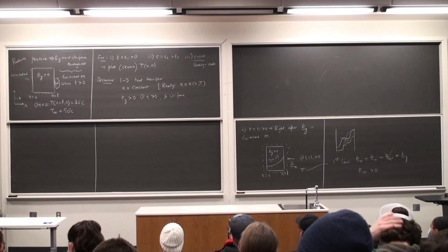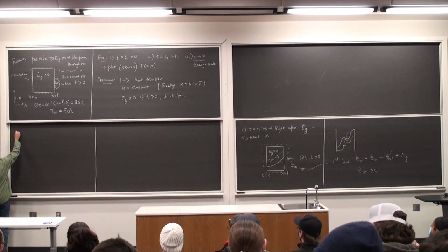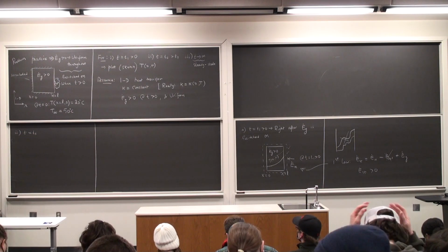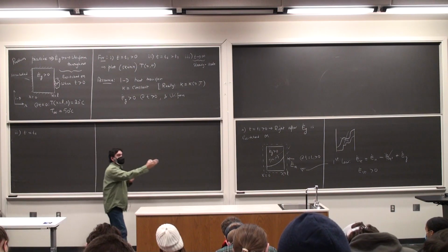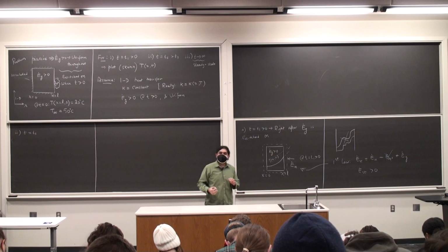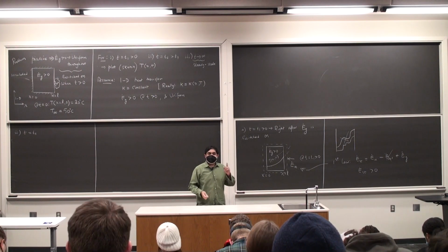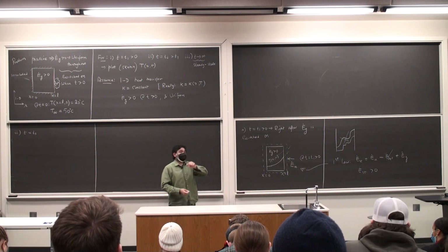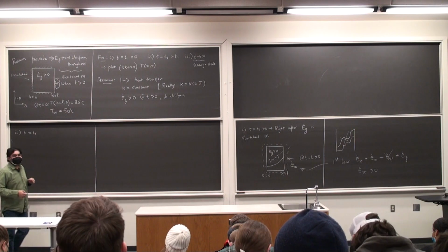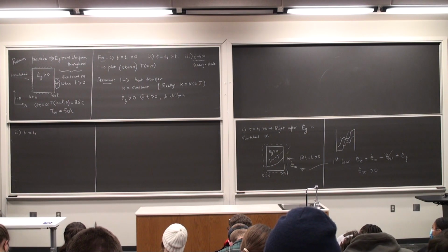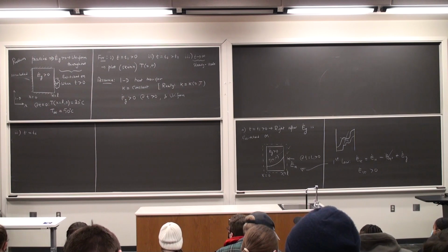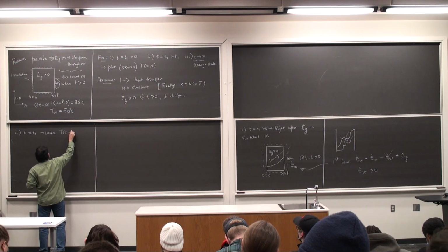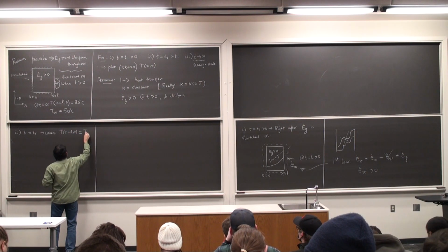Now, we will reach a time Ts, which I call a special time. What do you think is going to happen to the right side of the wall, x equal to L? It's getting hotter. Can it keep getting hotter infinitely? It's going to reach T infinity at some point in time. That's the special time I'm talking about, when the right side of the wall reaches T infinity, and T at x equal to L is equal to T infinity.